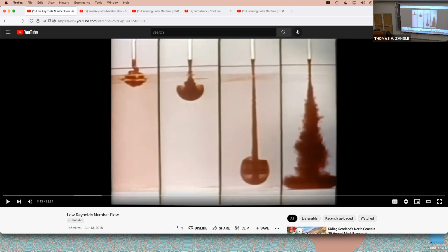It's very wide, like swirling as it's dropping. I think this is swirling when it's dropping because essentially the jet that you dropped in is not getting out of its own way. Imagine if you drop honey in, right? It kind of swirls up, kind of swirls on the top, because again, momentum is not important at all. So the stuff you're dropping in is not moving out of the way, right? I think this is really just the weight of the jet that you're dropping in, pushing the other fluid out of the way.